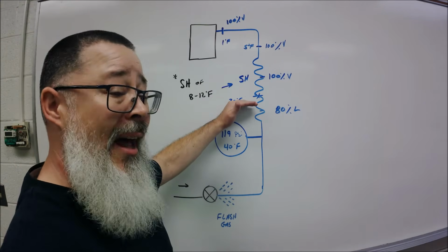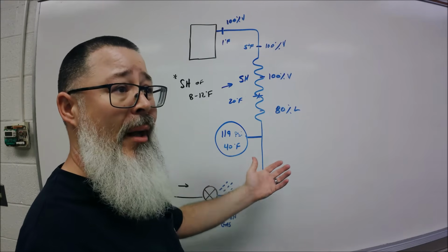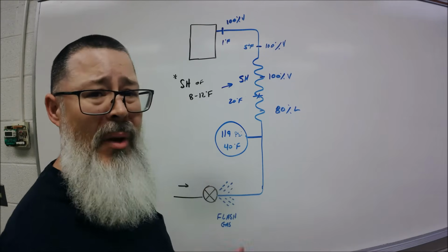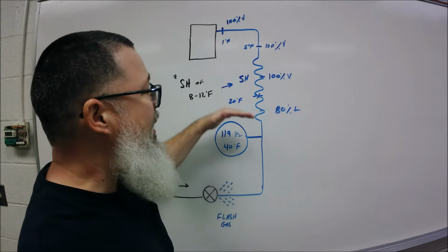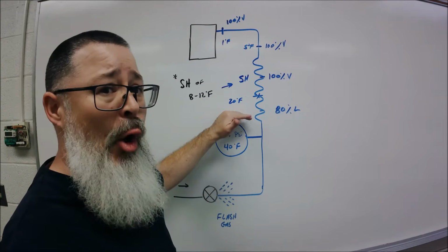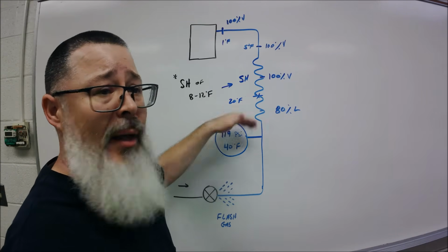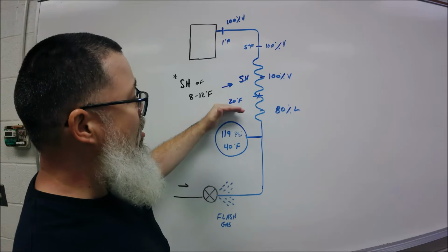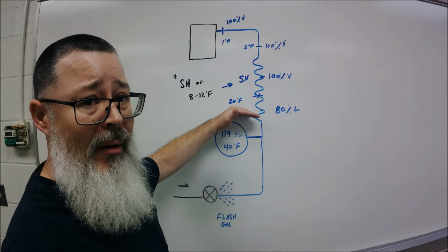So when you have a high superheat, one of the things we look at when we talk about a low refrigerant charge, why do you have a high superheat? Because for the amount of heat that you have, it quickly, early in the coil, early in the circuit, basically handled the refrigerant and turned it all to vapor. So the larger the number, the further back in the coil it happened, okay?